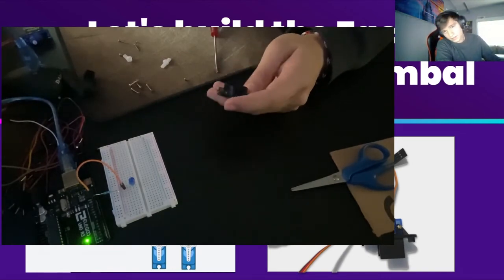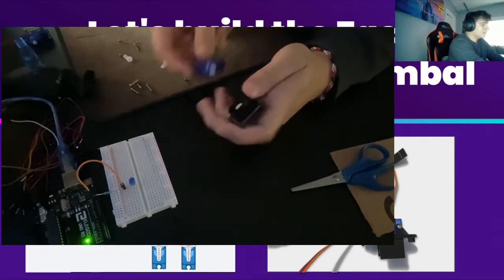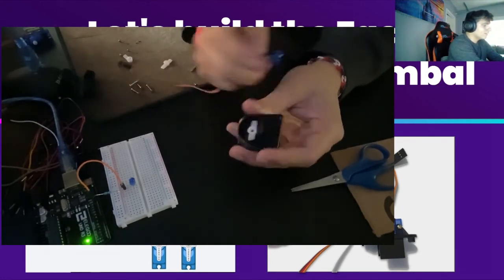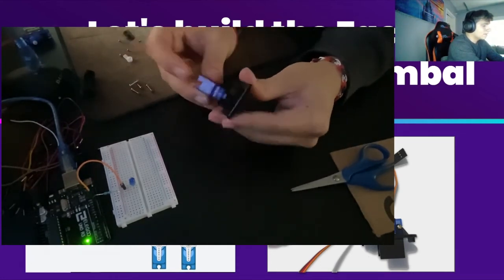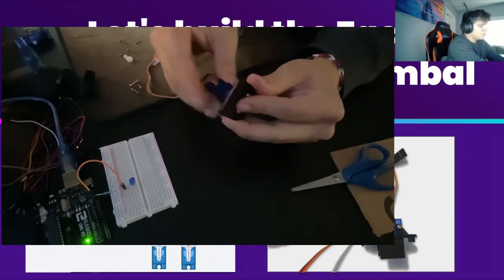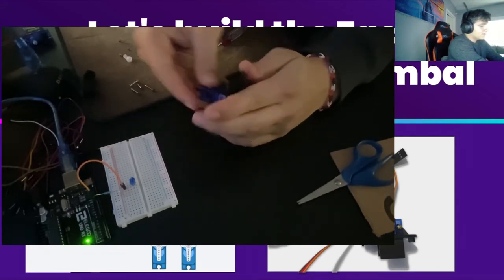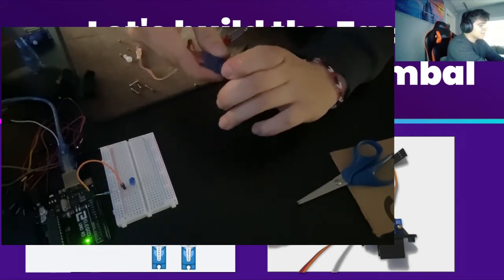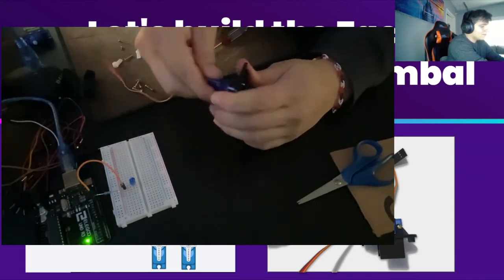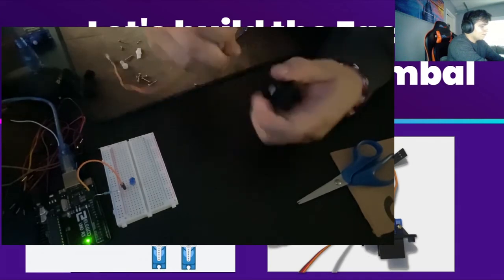Make sure to follow the orientation of the picture that we have here. So in that case, we're going to have it in this orientation. The long side of the base is going to go backwards, and then this is going to be pointing forward. Make sure that the servo is not locked on one side, because if it is, then we're not going to be able to turn it in the direction that we want to. So make sure it has a 180 turn from the middle.